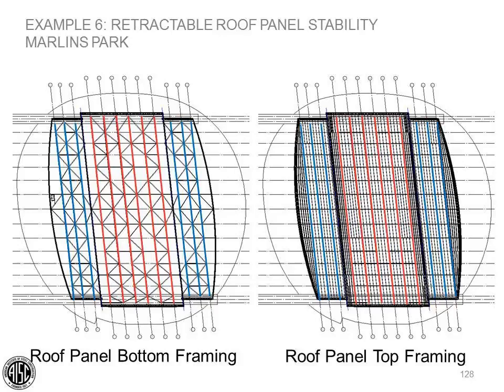Each roof panel is supported by a system of one-way trusses spanning on a skew from rail to rail. Each lower panel in blue has 3 trusses spanning 530 feet. The upper panel in red has 6 trusses spanning 566 feet. The trusses are up to 45 feet deep at midspan.